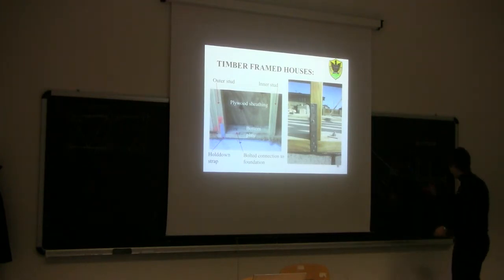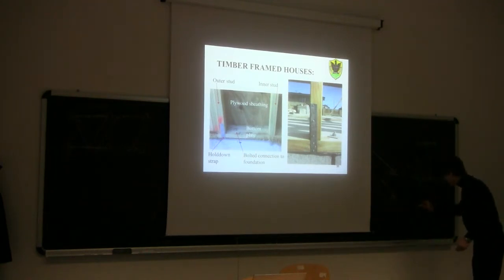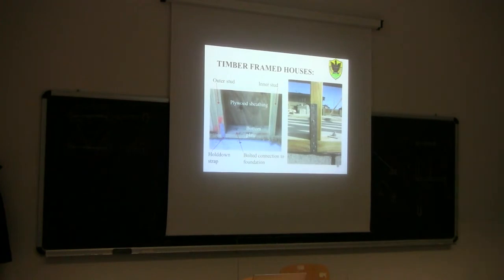So if I do a cross section like this, so this is the bottom plate and this is the stud, this connection here is done this way. It's a kind of U plate that simply connects the stud with the bottom plate. So it's not a real hold down.